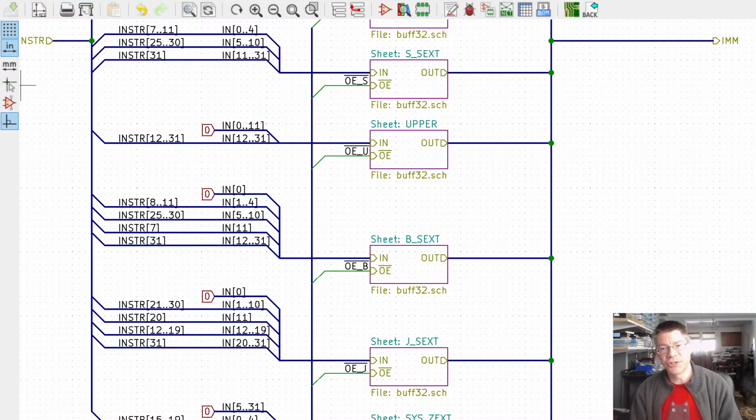And then there's the instruction cycle, and instructions can take anywhere between 1 and 3 machine cycles. So converted into system clocks, an instruction can be anywhere between 6 and 18 system clocks. I'm hoping that I can get a system clock up to 10 megahertz. That would be nice.